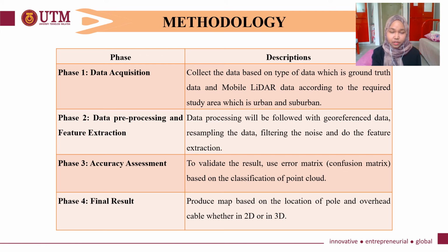In phase 3, accuracy assessment will be conducted after the feature extraction has been done. To validate the result, we use error matrix or confusion matrix based on the classification of point cloud to identify the accuracy of data. And the last phase is focused on the final result, which is to produce a map based on the location of pole and overhead cable, whether in 2D or in 3D.